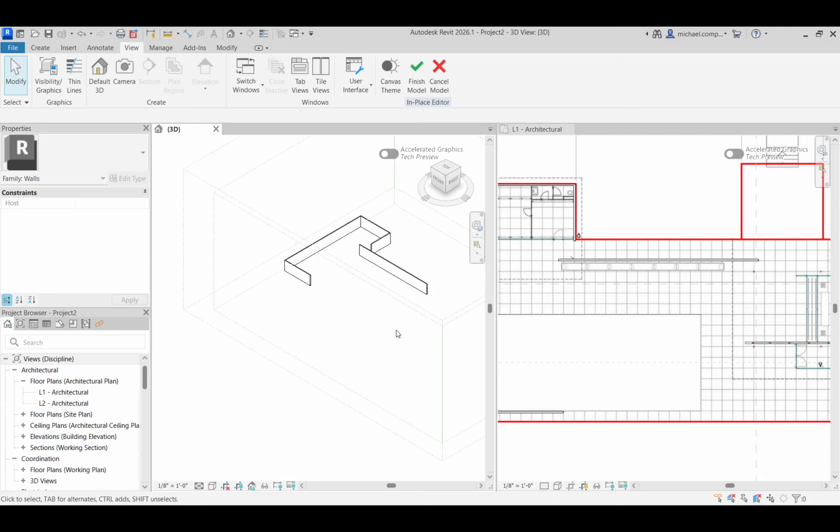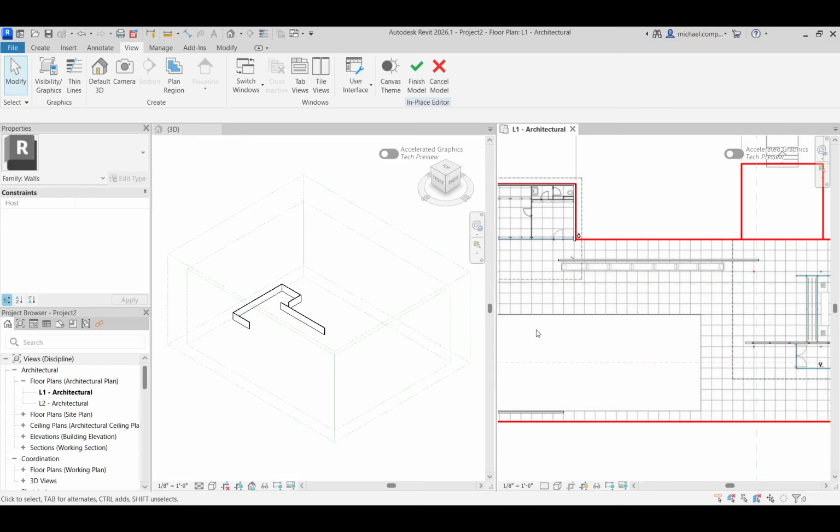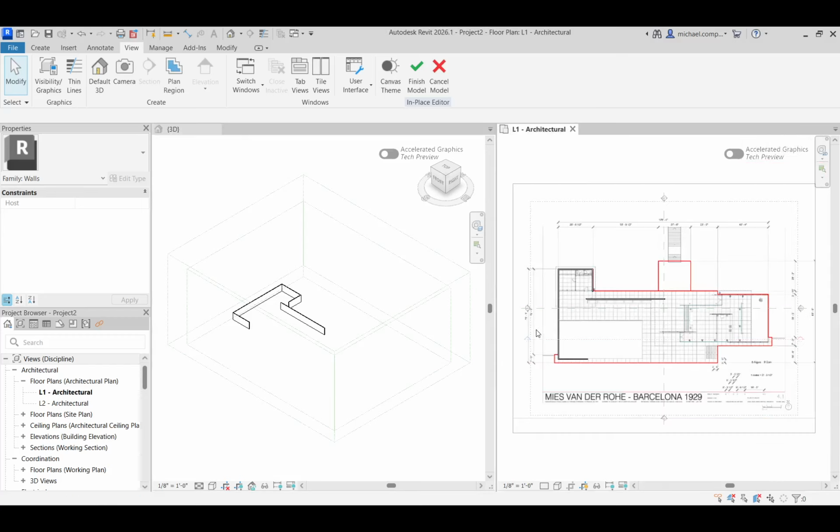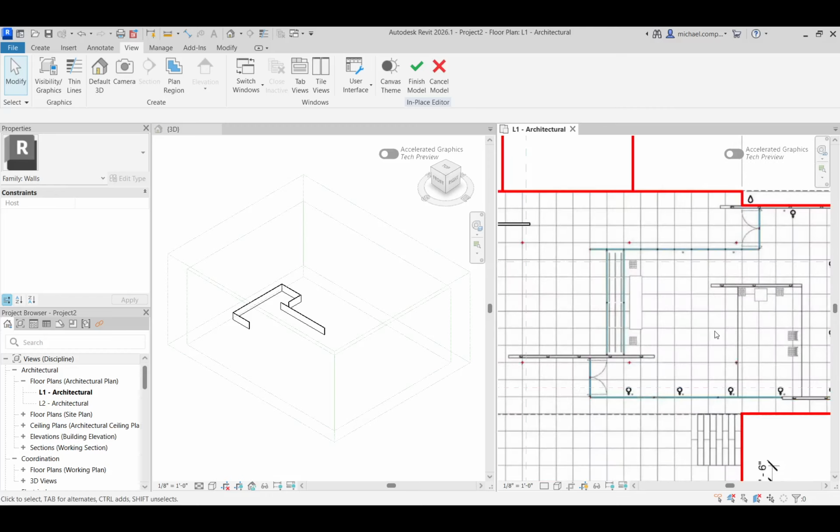And so ZE is one that you use a lot. ZE stands for Zoom Extents. So you type in ZE, just Z and then E, and then it'll zoom in whatever view you're in, zoom to the extent of that view. So I'm going to leave this one at ZE, but I'm going to zoom in and out of this guy.